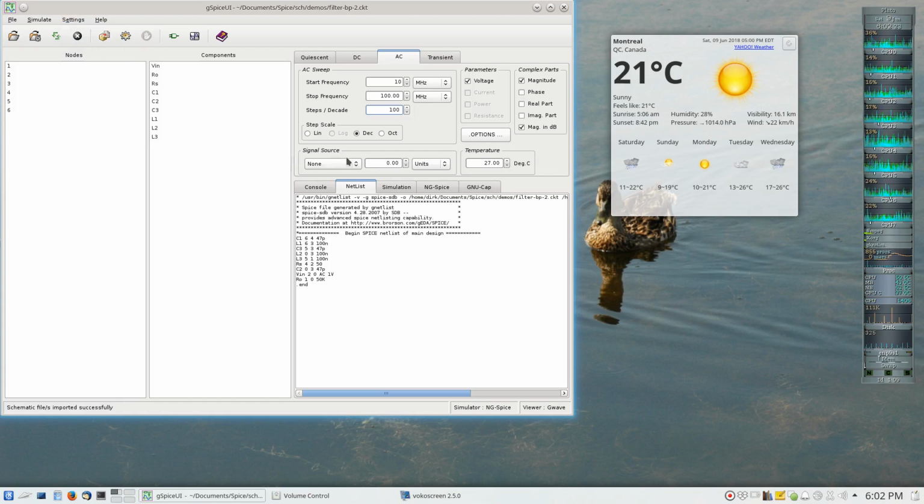Because I'm specifying that I want an input signal to generate output, I have to specify where to apply the input signal to. And there's only one real choice, and that's voltage in. The schematic is designed so that that's the only available input for my test voltages. And I would like to monitor what results on resistor output. The resistor output voltage, I can have the complex numbers treated in different ways that result from the output. I can have the magnitude in decibels, and I can simultaneously choose that I would like the phase position displayed.